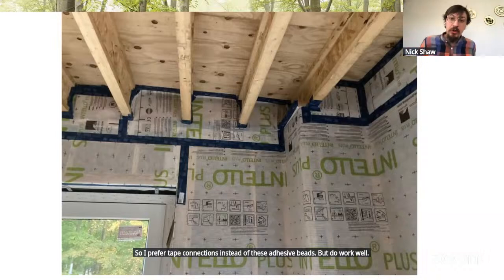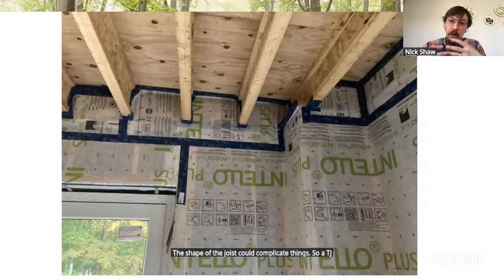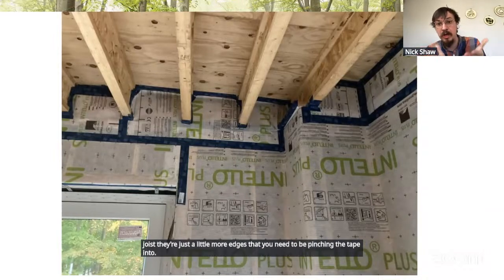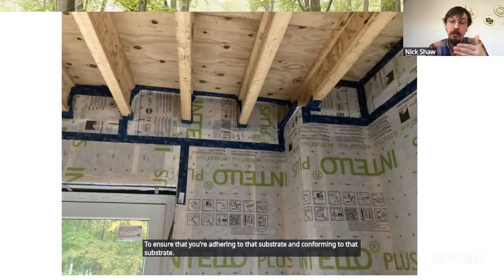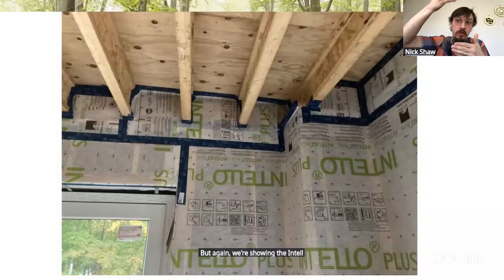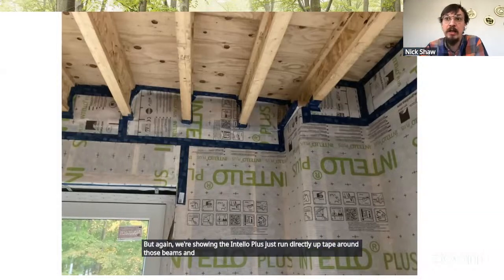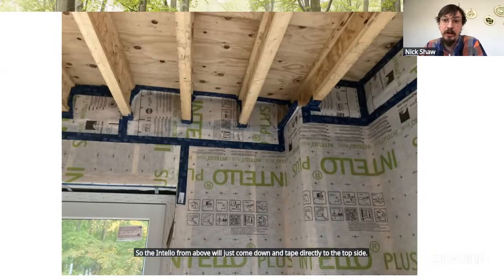The shape of the joist could complicate things. So a TJI framing, a wooden I-joist, there's just a little more edges that you need to be pinching the tape into to ensure that you're adhering to that substrate and conforming to that substrate. But again, we're showing the Intello Plus just run directly up, tape around those beams, and tape to the underside of that subfloor system. So the Intello from above will just come down and tape directly to the top side of that same subfloor sheeting.